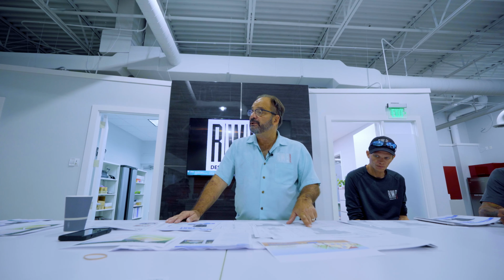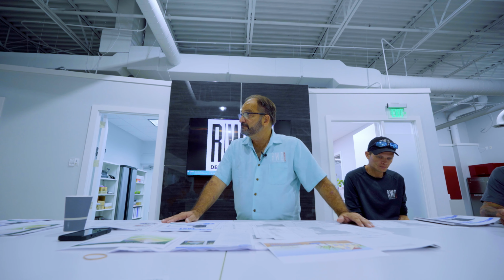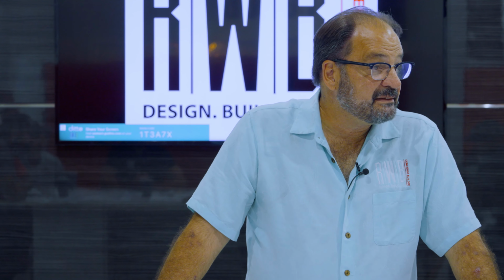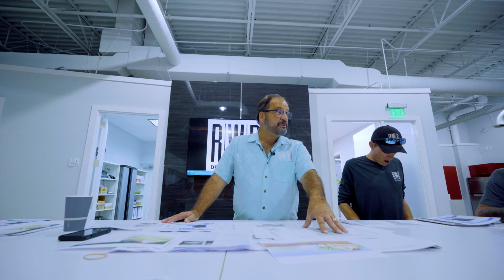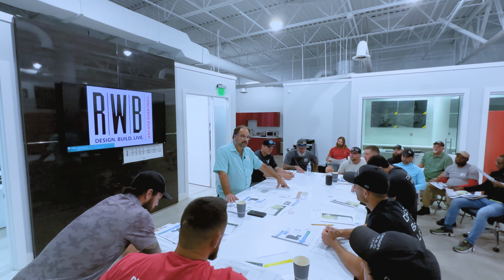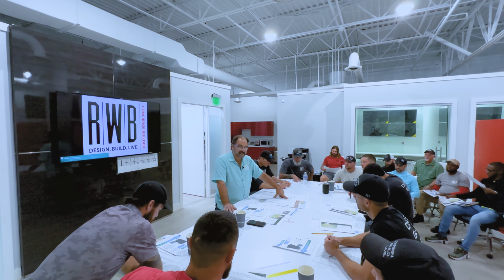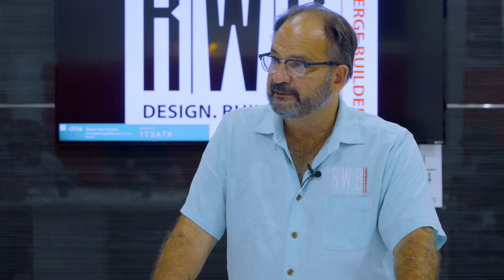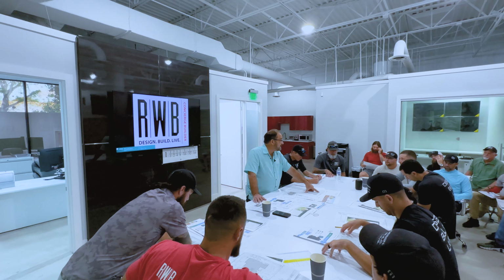You see the walls that you don't need. You see grades that don't work. You see a wall that is too tall. You see something that was missed. You have to go through this as if you're giving it its final review before build. Okay? You're the one putting your name on this. You're the one that's going to run this through the process. The guy who went through this before you is looking at it and says, yeah, that works. He's not looking at how you're going to build it. You guys have to look at this like a little inspector. And every one of you has to go through this and say, do these drains work the way they sit? Are these grades going to work? Can I cut this out?